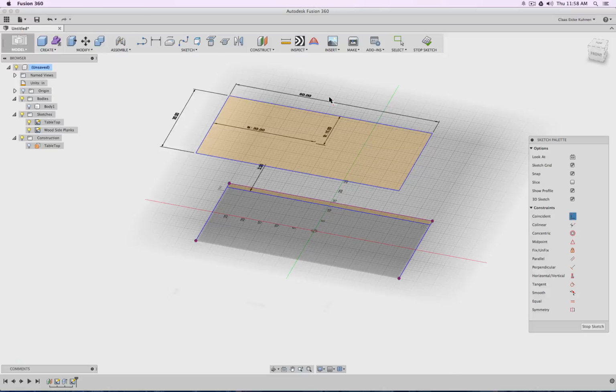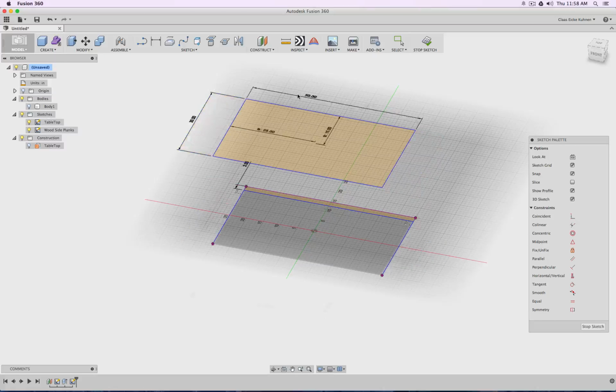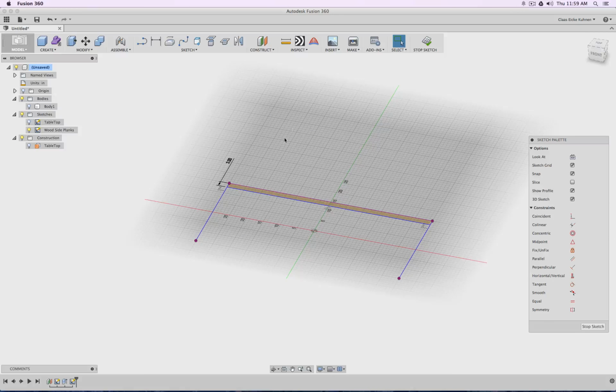And then actually when I change this one, you see it goes with it. Pretty awesome. So we set up basically another rule that this blue line is always 2 inches away from this magenta line, which is a projection of this edge down. And then the endpoints of this line are always coincident to the line that is created by snapping to this point and this point, again projected from the top sketch. Again, this is an example for how you actually drive designs.